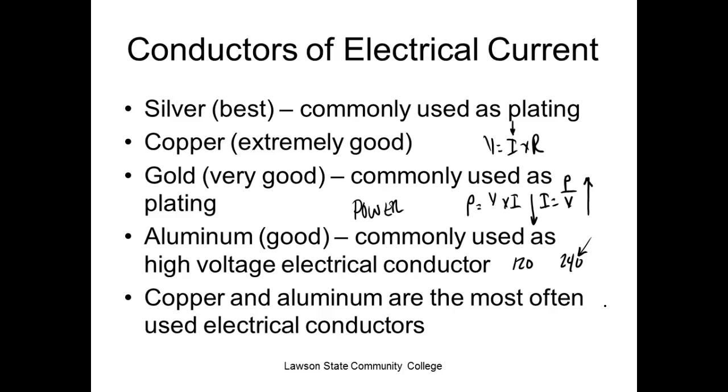The problem, guys, is I've got to run that 1,800 watt heating element on my stove. If I was to do that at 120 volts, the wire that I would run out there would probably be like 4-gauge wire, and it would probably be about that big. And anything less would melt. So the only real advantage of high voltage is it takes a smaller conductor to provide that power. So all your high wattage devices are run off 240.